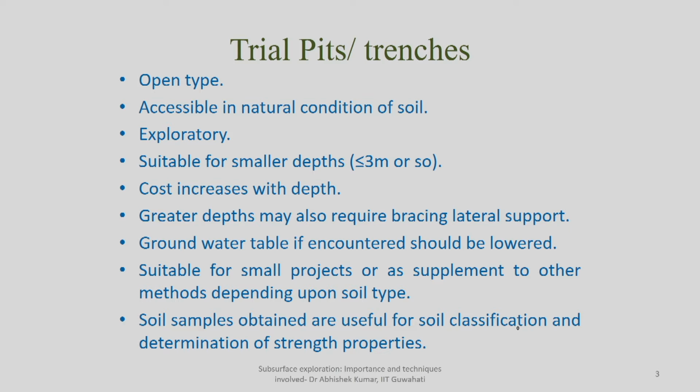These are basically open type. We need not go for any small borehole or deep excavation. It is open type, and you can go maximum up to about 3 meters depth, as is accessible. You try to collect the soil sample which exists in natural condition, because you go to the site, start excavating, and then try to retain whatever soil you have excavated in its natural condition. These are exploratory methods.